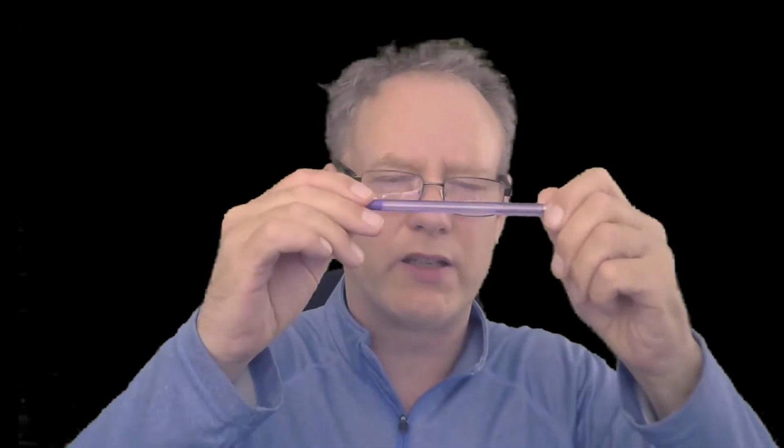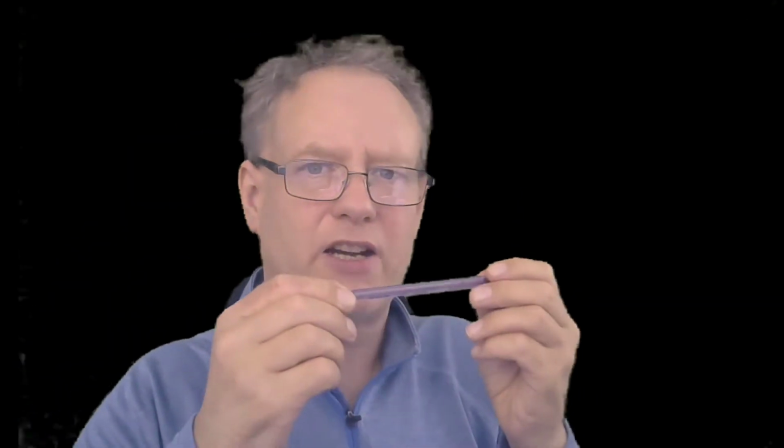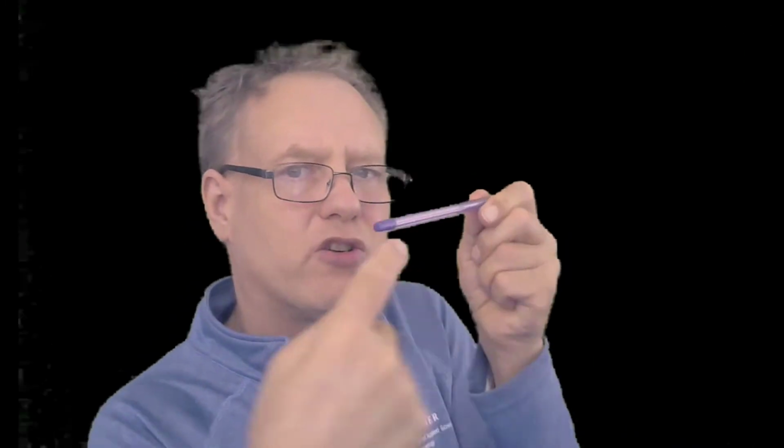When we talk about magnetism, Faraday's a really cool guy. What he did was he took a conductor. Let's just pretend that my pen's a conductor. And he put it through a magnetic field. He found that when he moved it through this way, there's EMF. What's EMF? Electromotive force. There's actually a force pushing the electrons either that way or that way. And if we have a loop, we have current. That's pretty cool. So, alternating current.